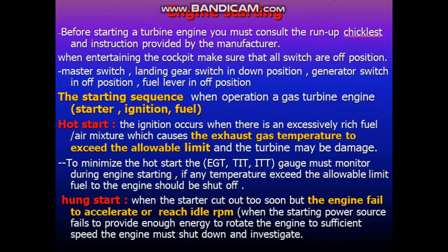The master switch and the landing gear switch should be in the down position. Also the generator switch must be in the off position, and the fuel lever in the off position. The starting sequence when operating a gas turbine engine: when you turn on the switches, you have to start with starting, then ignition, and after that fuel.